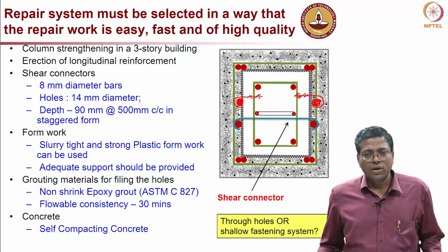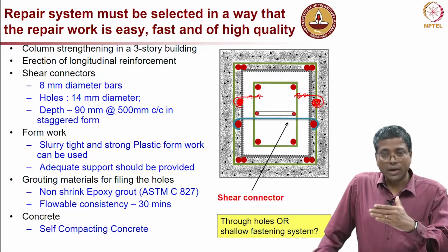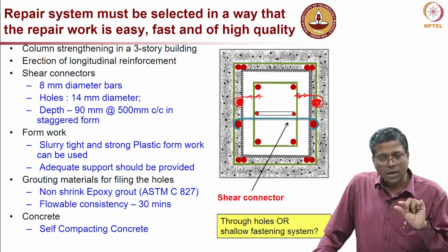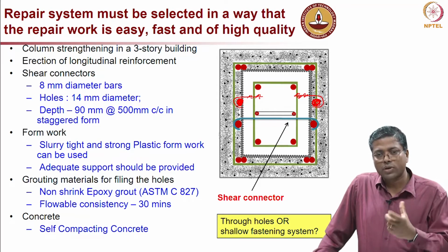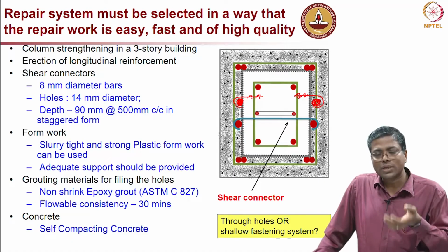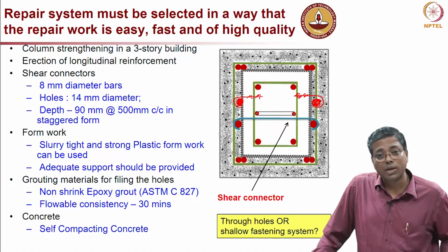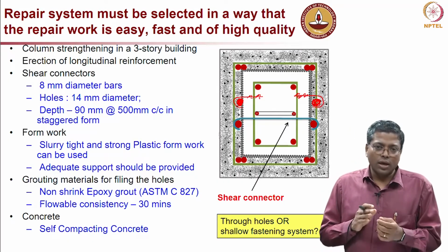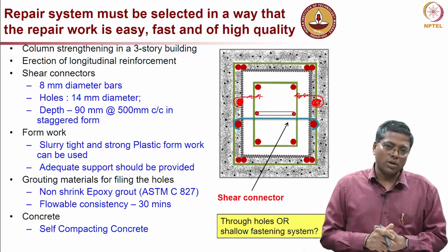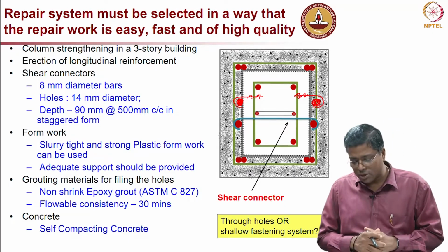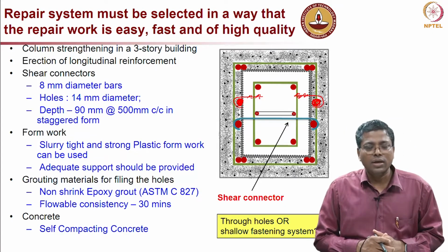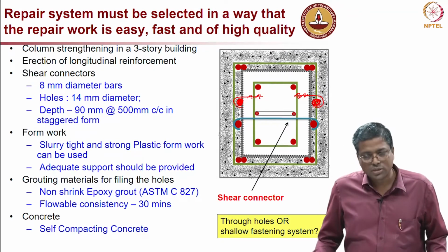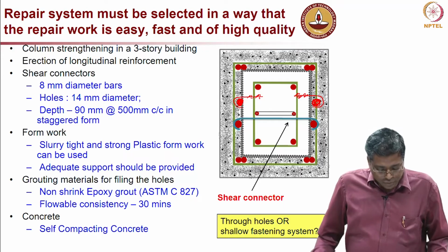So, this is enough, or this kind of design can be conceptually looked at and then designed accordingly, whatever the diameter of the hook, length of the hook, or embedment length. All of those can be designed, but conceptually this might be a better practice than expecting the workers to get this hook done on the column. It is important, because sometimes some designs are not really easy to adopt, or the feasibility is not that good.